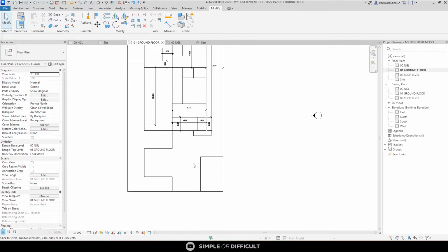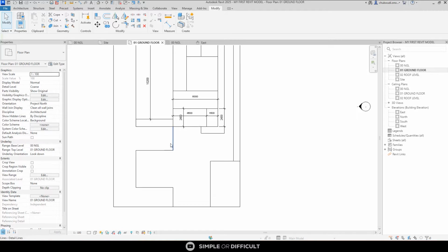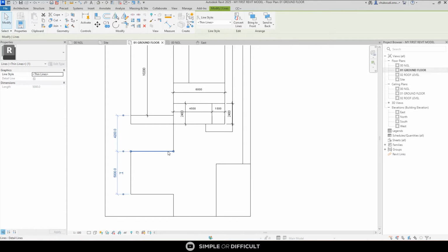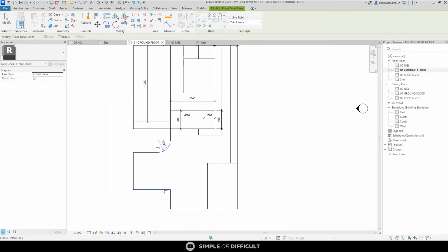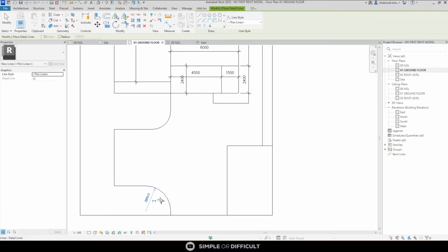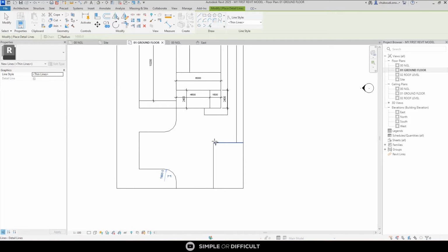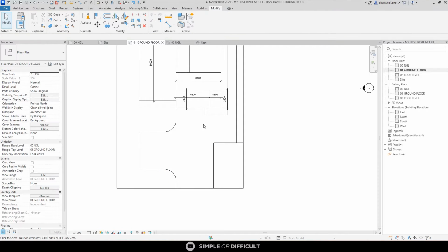When the time comes, we're going to fillet the places that we need to fillet. In case I want to do it now, I just create similar. This is it, fillet arc. I will just do it like this. We'll just make this 1.6. The same thing for this side, 1.6. And that's basically it.